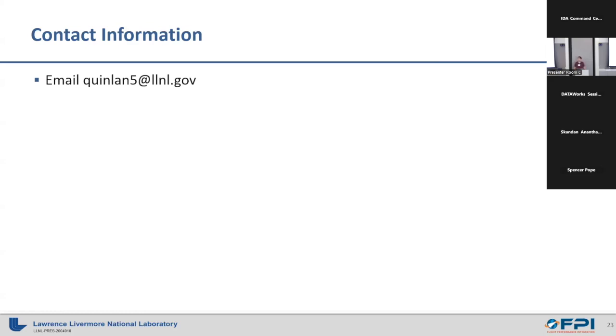Yeah, I guess the way I'd be thinking about that is, you could definitely apply the wind tunnel testing data here. I would think the way you'd want to try and do this is maybe build it up as a multi-fidelity model. And so you could use whatever you've done from your mod sim to give you a better initial idea of where to sample or to run your wind tunnel tests. I know there's some different constraints with testing for the wind tunnel, but certainly we could use that to help inform where you'd want to run the tests.